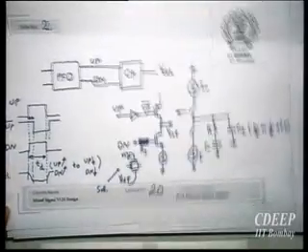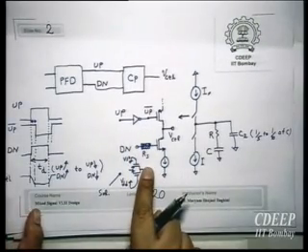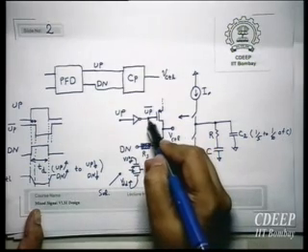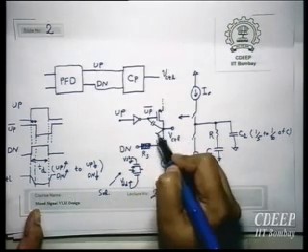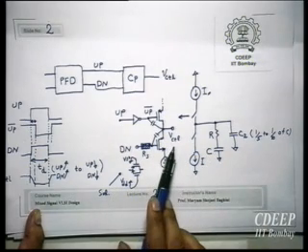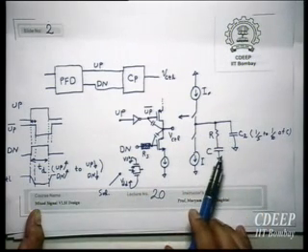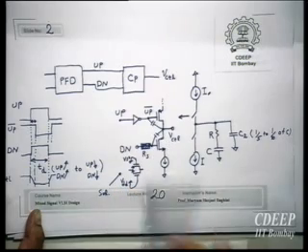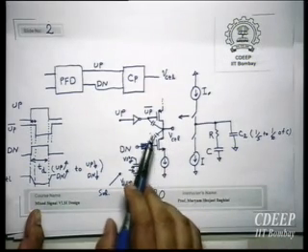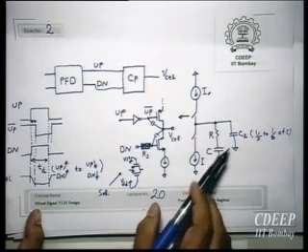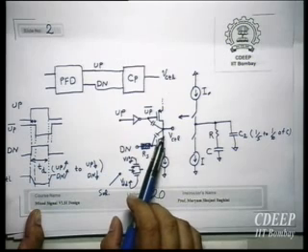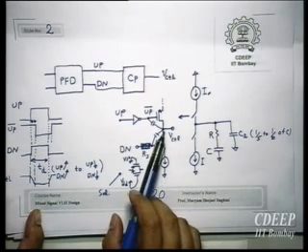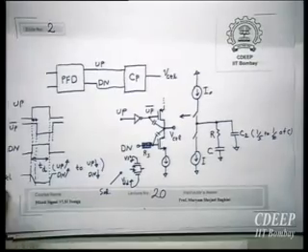Another point is, as we discussed last time, because these up and down signals are fast, because of these parasitic capacitors there will be clock feedthrough onto VCTL. And there will be another phenomenon which is charge injection, because here I have capacitors. So we will show how charge injection affects. So in addition, even if everything is ideal, depending on the magnitude of these C values, practically we may have some small spikes on VCTL due to clock feedthrough and charge injection.